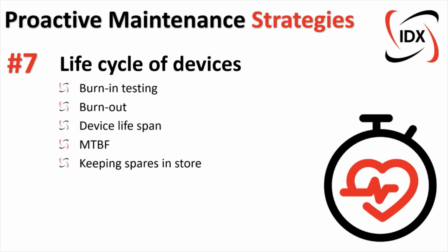Keeping spares in store is excessively important, especially for devices that have a very long lead time. And I know some of the vendors for spares, especially such as PROFIBUS interface cards, can take months to supply a spare. And you really don't want to have your plant standing because you can't get hold of a $200 PROFIBUS interface card for a VSD. So keeping spares in store, especially for critical components, is excessively useful.